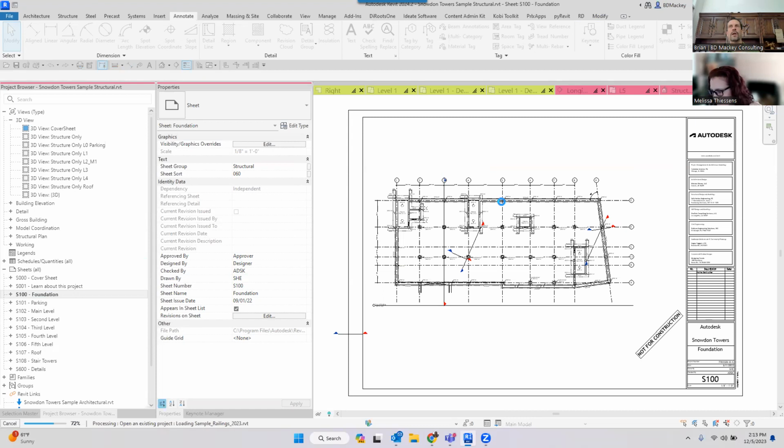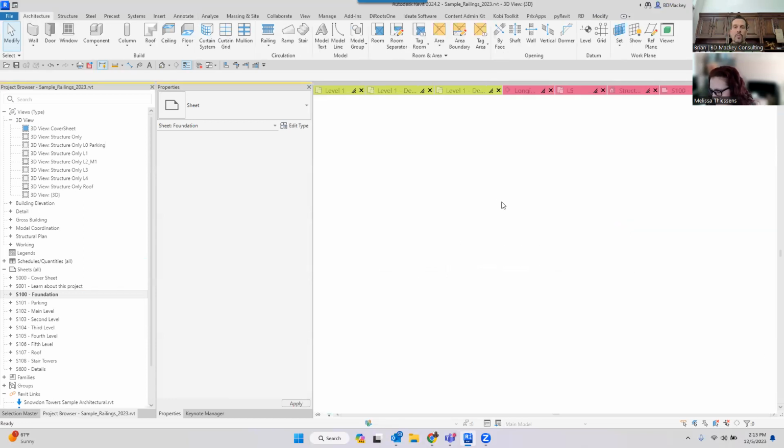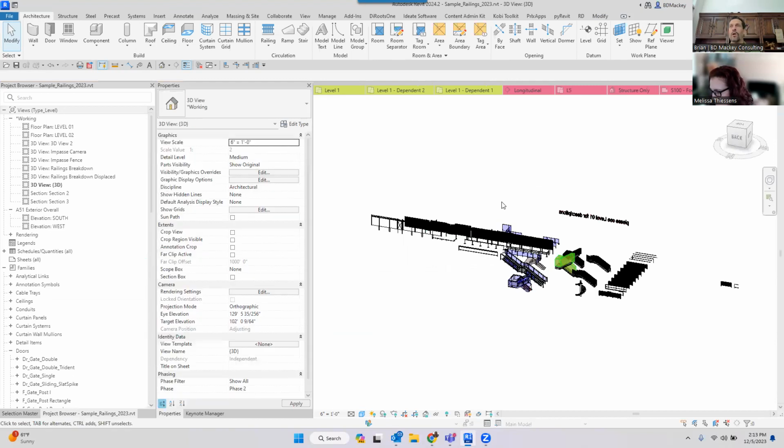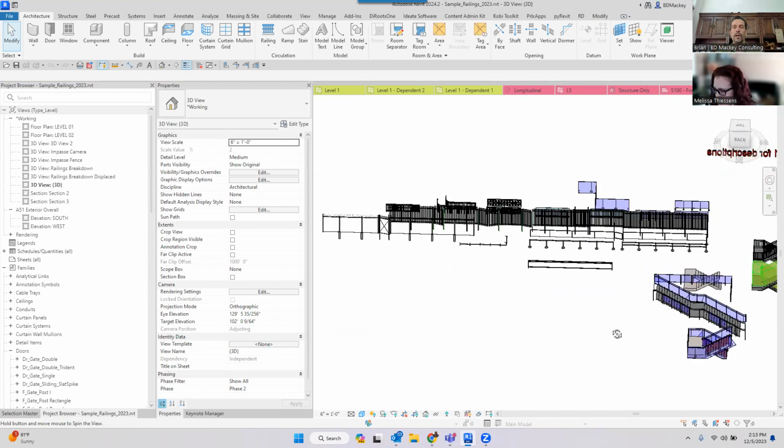But I think for me, 90% of the time, I do railings as railings, and I'm pretty successful using the railing tool. I know Tom, who's on here, tweeted a while back, "Hey, how do I do spiral barbed wire?" And for me, that's very simple and easy to create as a railing. I also think railings are great because, A, they're going to follow the slope of the stair automatically, the slope of a wall, as you said, the slope of site, etc. But you can do a lot with the railings as long as you start breaking them down.